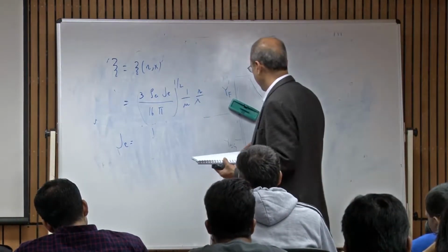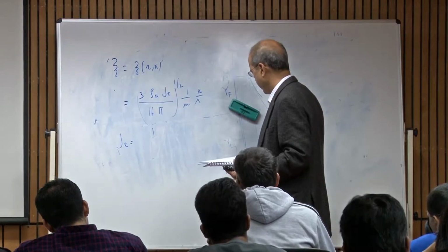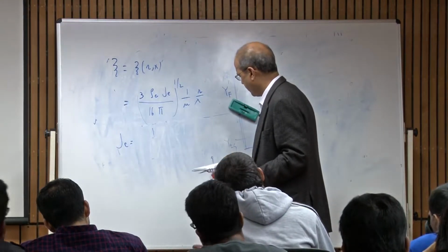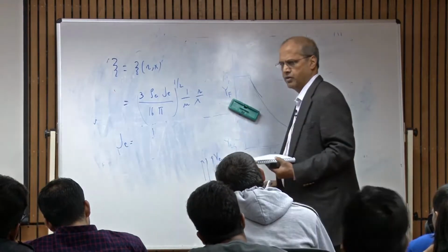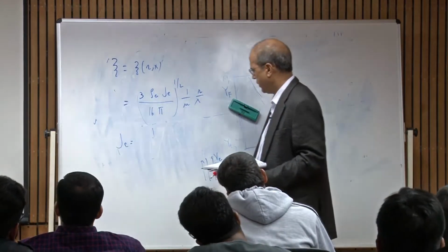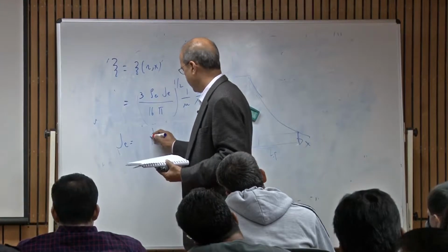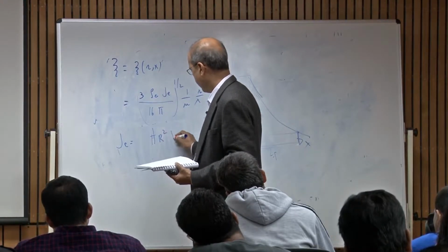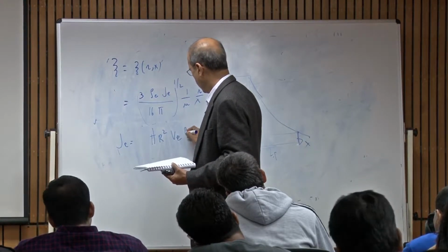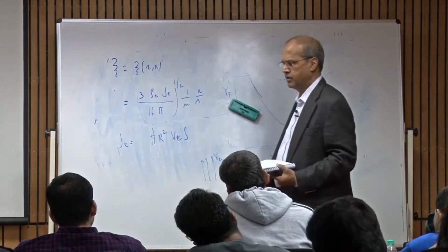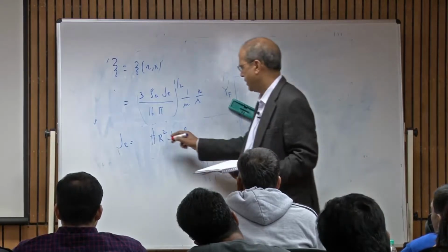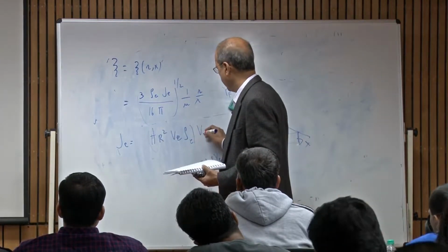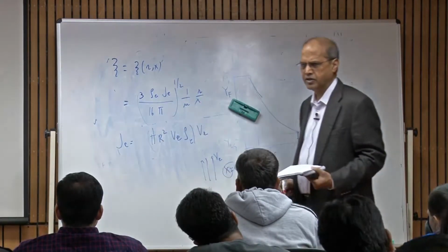So at x equal to 0, you have the uniform velocity Vx, which is Ve. So the momentum flow rate will be the mass flow rate, rho e times the area and velocity, and the momentum flow rate then will be times V. So that's a constant.